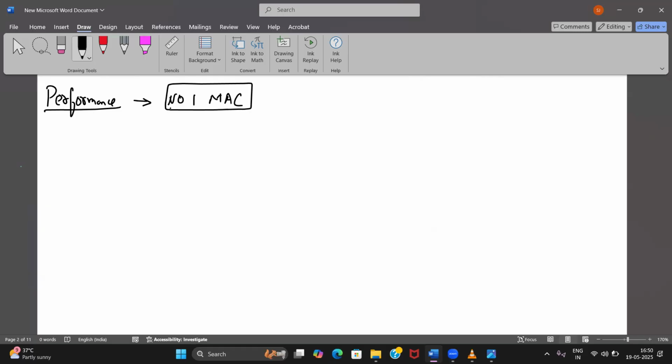Anyone? We will check the pressure gauges. We will check how much time the air bottles take to get filled, and match it with the manual to see whether its performance is good or not. Excellent.